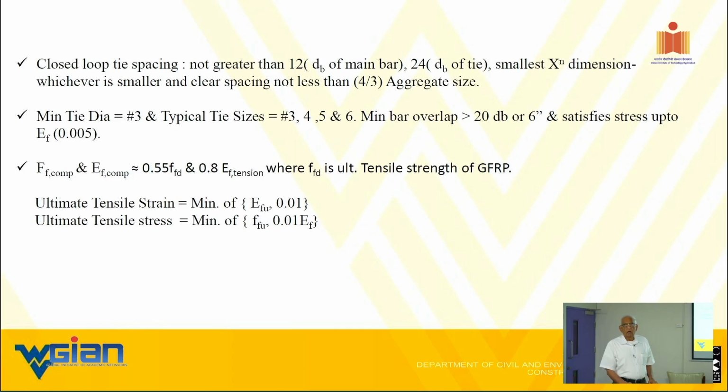Average of the ultimate, the average of all the 10 tests. But that is not what they report as a minimum guaranteed value. That minimum guaranteed value is the average minus 3 sigma. Assuming sigma is 8%, some number like that, or 6%, 6.5%. So that is multiplied by 1 minus 3 times 6.6%, that's 0.8.